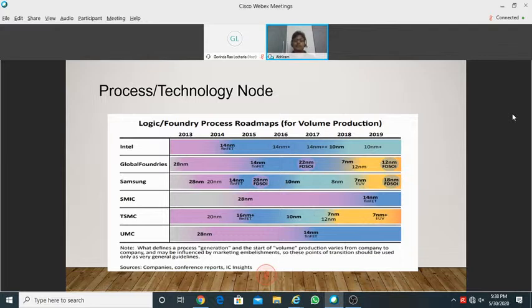With 7 nanometer we are putting more and more logic and more computation, and lots of effort goes in, because we can't go to 7 nanometer for every other thing. We need to go to 7 nanometer only if we can pack that much logic, otherwise volume and cost effectiveness will not be achieved.